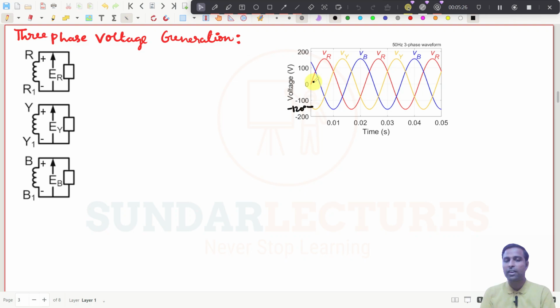So this Y phase lags the R phase by 120 degree. And then you see this point, this is plus 120 degree, which means this B phase leads the R phase by 120 degree. Always you see the three phases R, Y, B are all separated by 120 degree, all apart by 120 degree.